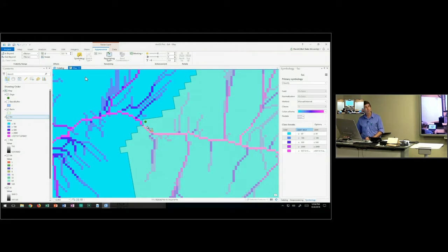Some of these latitude and longitude coordinates came from early survey work. Also, you'll notice that the watershed boundary we got from the watershed delineation tool is dealing with bigger grid cells than the 10-meter DEM data we're working with. I think it was dealing with 30-meter DEMs, and it's also skewed off to the side. It was actually using a national coordinate system, not the local coordinate system for this area.